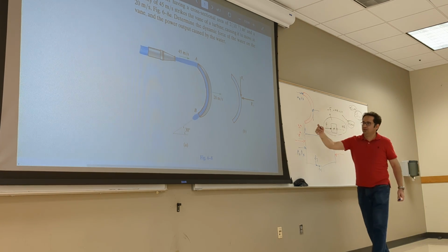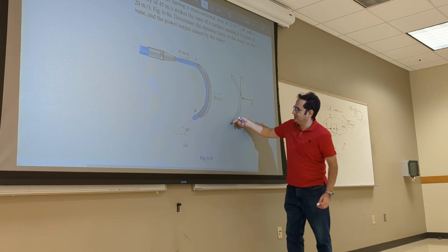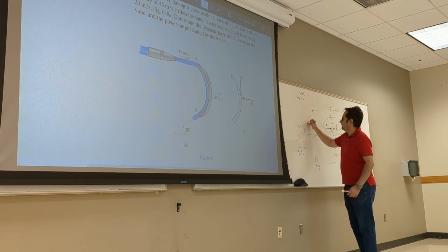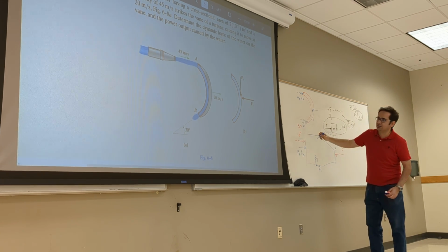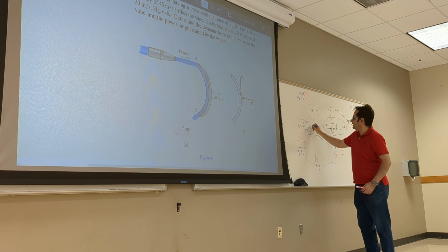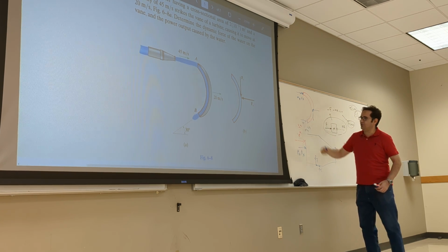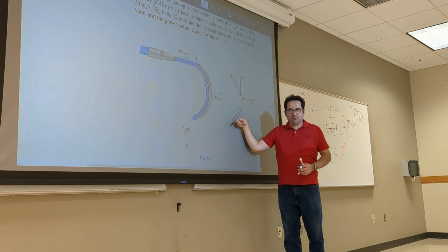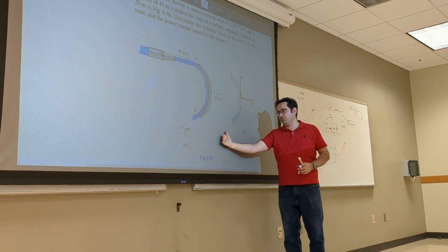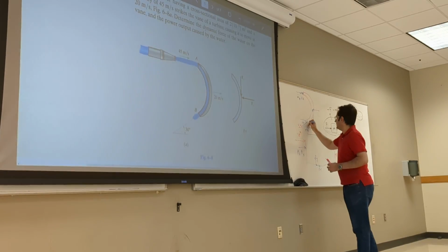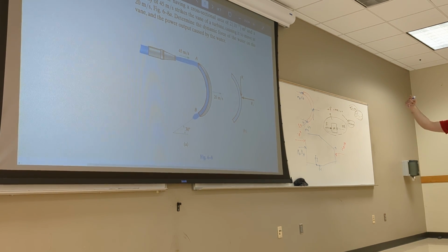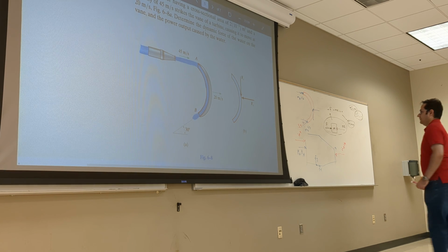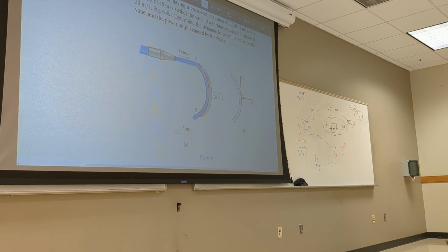And then what about this point? The velocity is leaving. Now let's say this has an angle here, so you have an angle like that. So what do you put here? m dot V_B. But is that the direction of the inertial load? You have to compute it. Velocity m dot V is this way, times V this way, so put the opposite this way. m dot V negative times that again positive, that's it. So these are inertial loads.